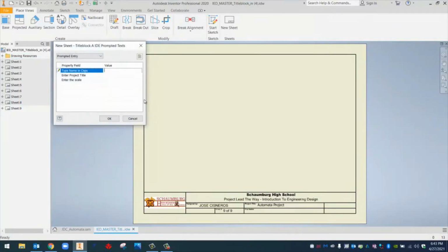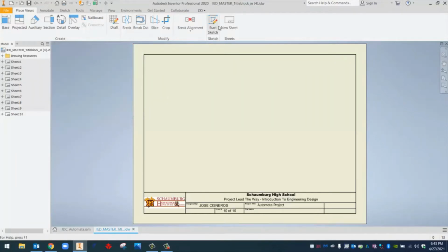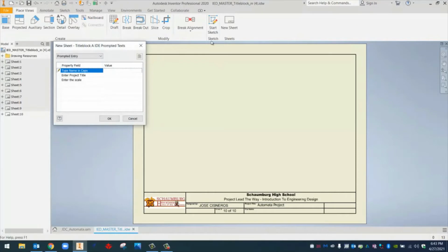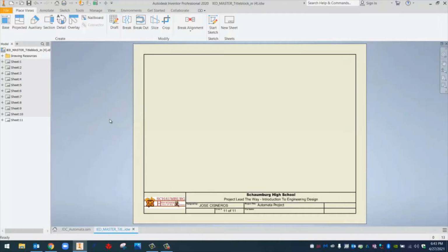What's going to be included in these sheets is going to be multi-view drawings with dimensions. That's going to be the most important thing to communicate our results and communicate our design. You could even do this for yourself. So say you're trying to build something in your workshop, where you have all your materials, but you're designing this on a computer, maybe on your laptop or your desktop. You maybe can't bring that into the workshop. The best way to make sure that you know your measurements for all the parts that you're going to be cutting and things like that is through a working drawing like this.